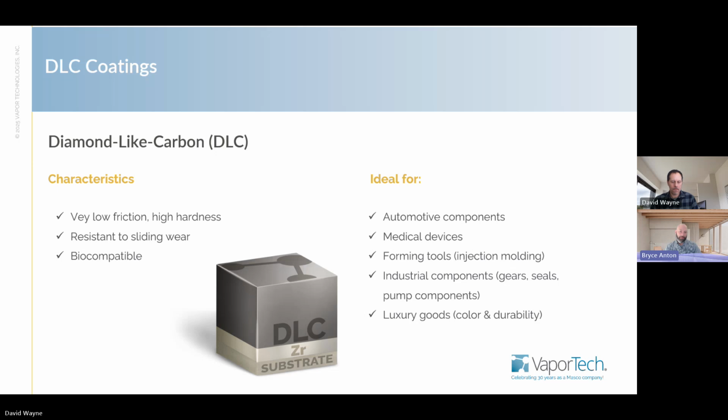Absolutely. DLC coatings are really exciting. There's a lot of great functionality that we can get from DLC coatings, but just to be clear, the word DLC is used a lot. It basically just means diamond-like carbon. So these are carbon-based coatings that have some level of diamond-like properties, meaning the bonding of diamond is part of that makeup. They're usually a mixture of different bondings, and often they're hydrogenated, so they're never quite like pure diamond. But that's okay, because you don't necessarily want pure diamond hardness in most of your applications, because that would be much too brittle.